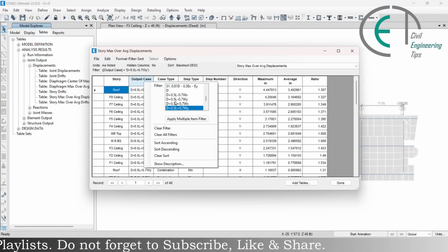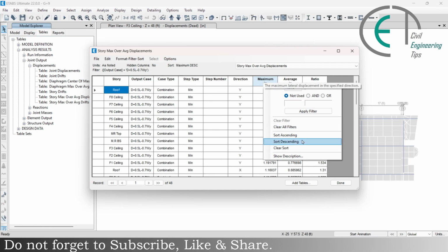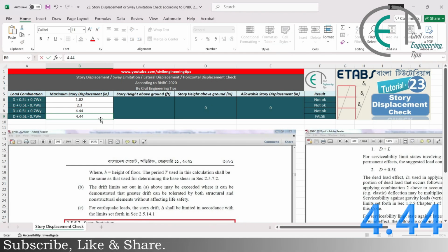Similarly, we can right click and choose this load combination and right click here and choose sort descending, and we are getting the value as 4.44. We got the similar value and we are inputting here 4.44 and pressing enter.